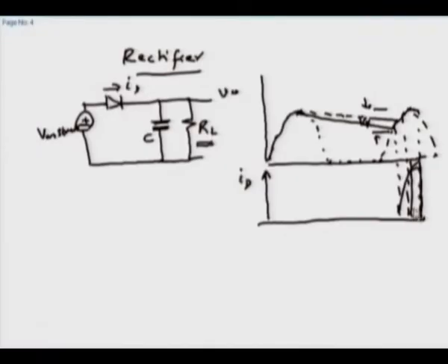So, this is something which is to be kept in mind very often. In a power supply, therefore, the solution is to reduce ripple. The solution is not to put a large capacitor, rather to put some reasonable value like 1000 microfarad or so. The solution is to use voltage regulators.